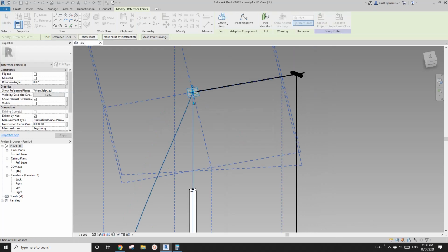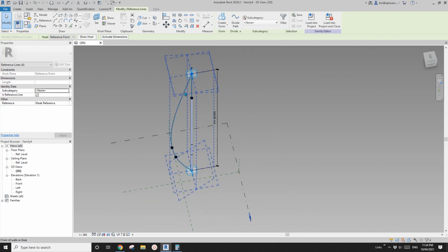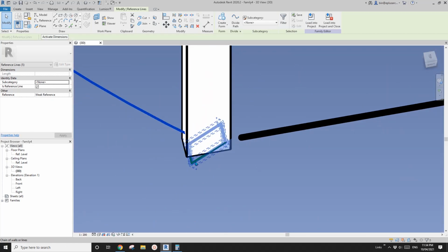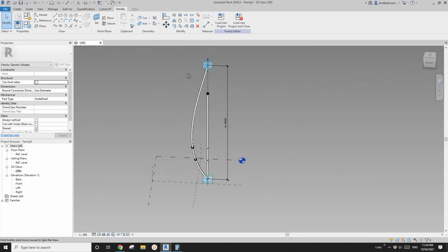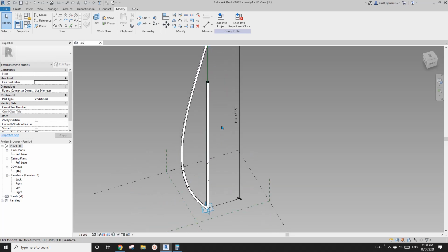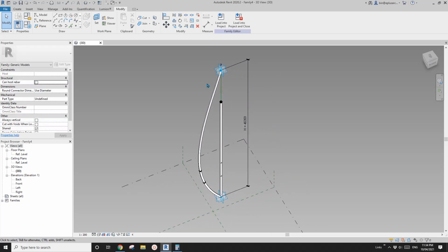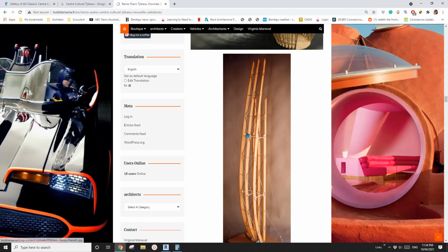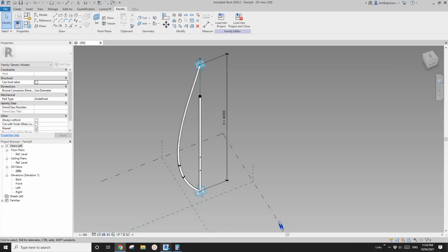And then you can select this profile, making sure you only select this curve, so tab, control select, and also this, okay, control select and create form. So now this is the curved one. Okay, so now this is it. We'll just try to keep it simple for this exercise. So now the next step, we need to create this shape. Okay, so let's do it.